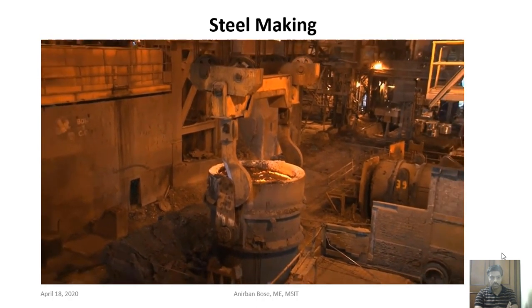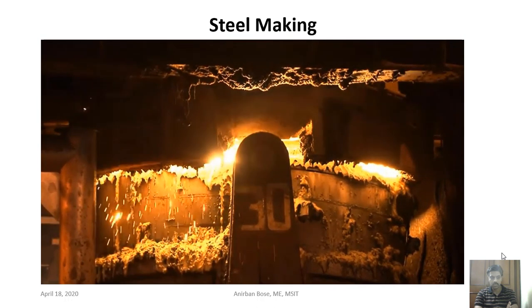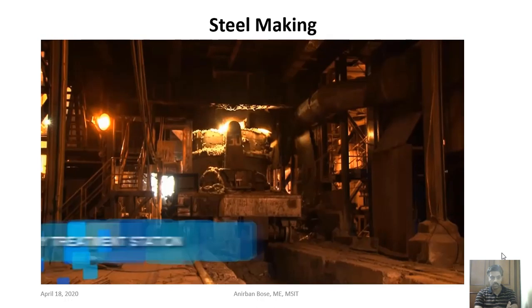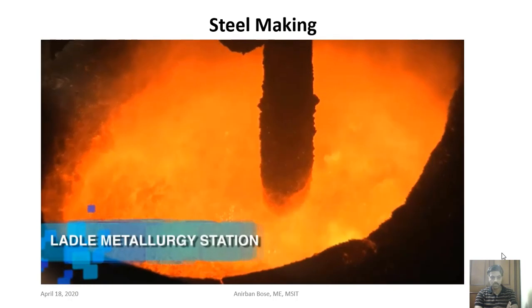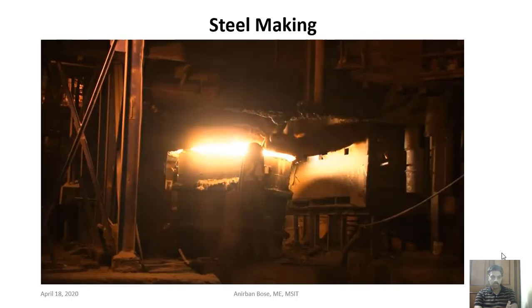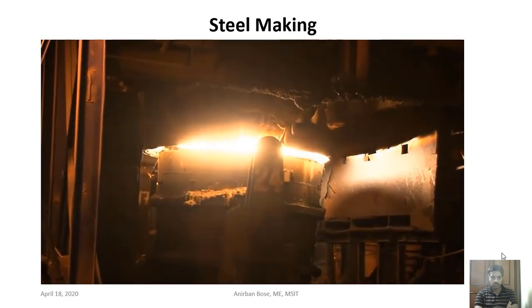into special ladles. In order to produce specific properties, the liquid steel from both systems goes to the secondary treatment station: secondary metallurgy, ladle metallurgy, or chemical reheating. Likewise, liquid steel can be processed in the dual degassing station to reduce the content of hydrogen and carbon for applications with higher requirements.